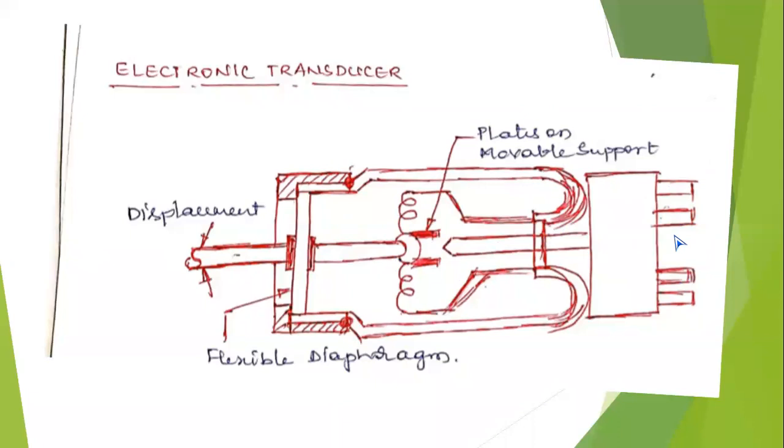Then see that all the switches are on. Switch on all the contacts. Connect all the 4 terminals to the milliammeter and then move the plunger on the surface plate. This plunger is connected to the diaphragm.